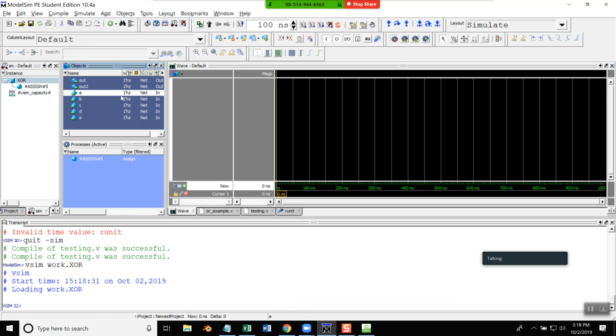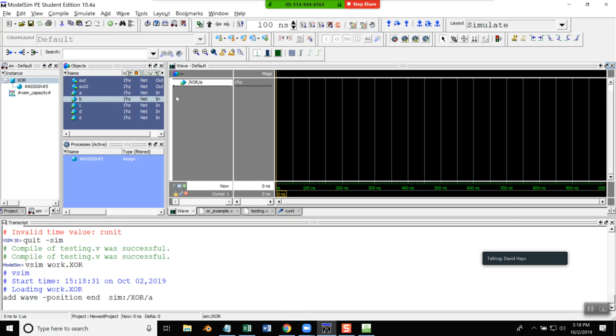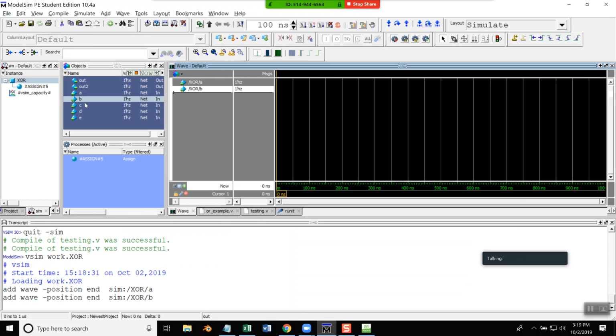But again, I could add 5 more variables in here. That's 32 rows. That's 64. That's 128 rows. That's 256 rows. And that's 512, 1024. I wouldn't even want to try to do a truth table that has that many. But with a simulator here, we can easily put whatever we want in. You just have to know the proper syntax.